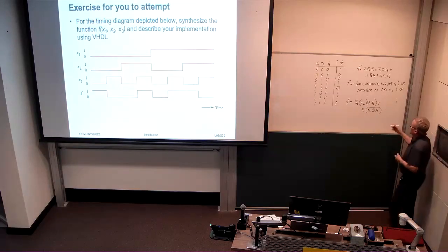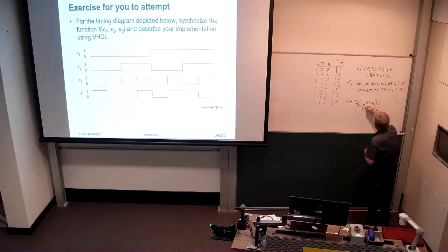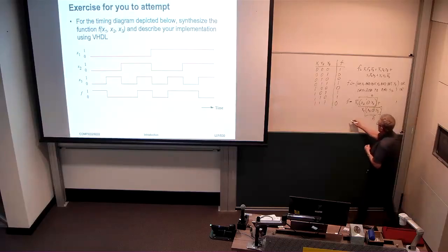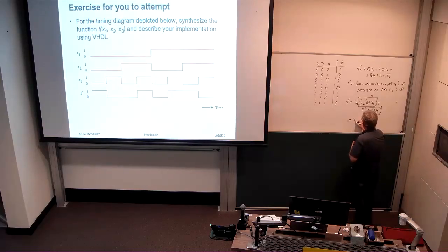And it just so happens that we could substitute for this bit here A, for argument's sake, then this becomes not A here. And that in turn is the exclusive OR of x1 and A. And so we could just write x1 exclusive OR x2 exclusive OR x3.